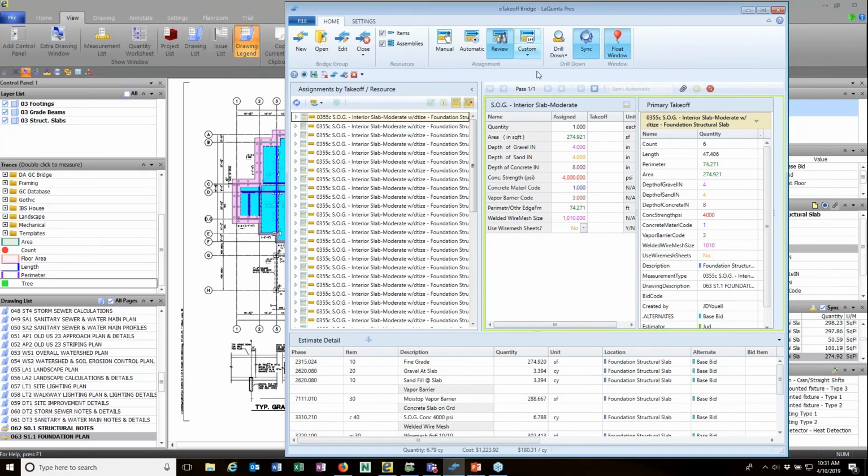One other thing I'd like to throw out: remember where I mapped the description up to the assembly name? I was working in 2D. That would be very handy working in 3D. If the architect has named a particular wall type, then you could include that wall type on your estimate, or you could even replace the assembly name with the wall description from the BIM model. So there are some interesting things you can do with mapping in 3D.